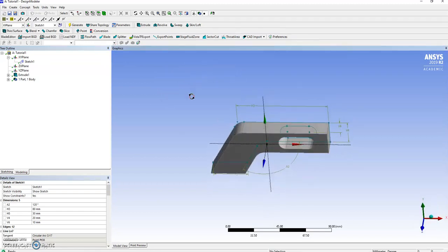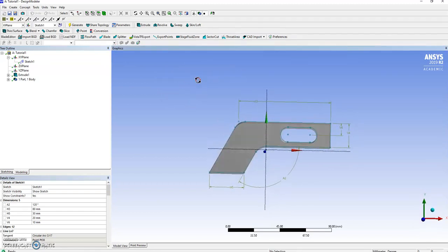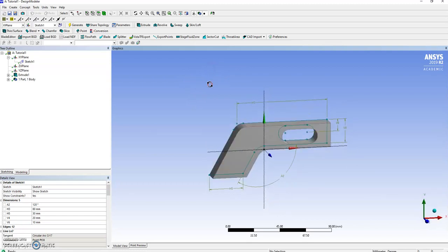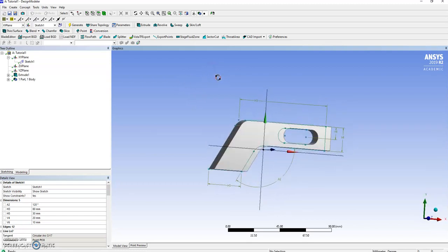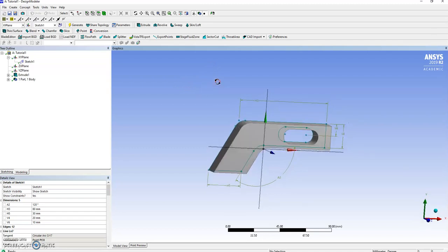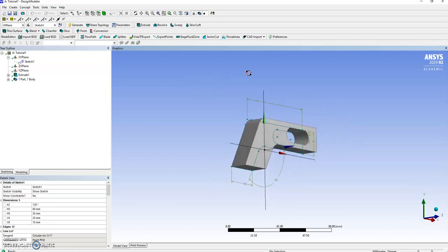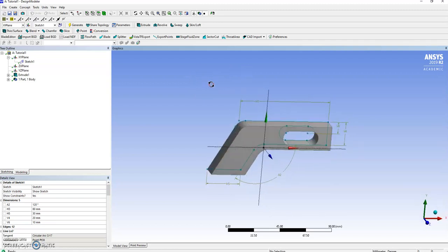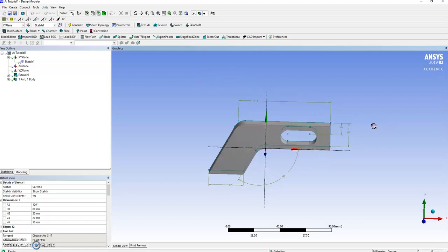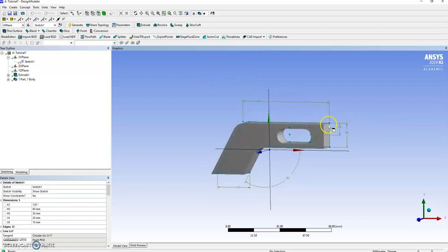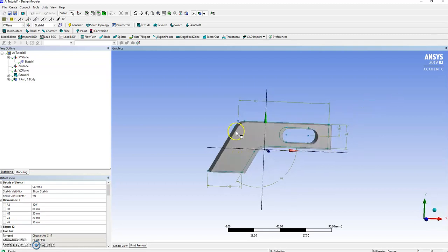It looks all nice. Okay, so there is a lot more to DESIGNMODELLER than just that, but at the moment, it's good enough. We'll look at it later. Ah, no, I keep forgetting something. Something that is important is that, let's say that I will fix the part here, but I will want to apply a load only on a portion of that face.